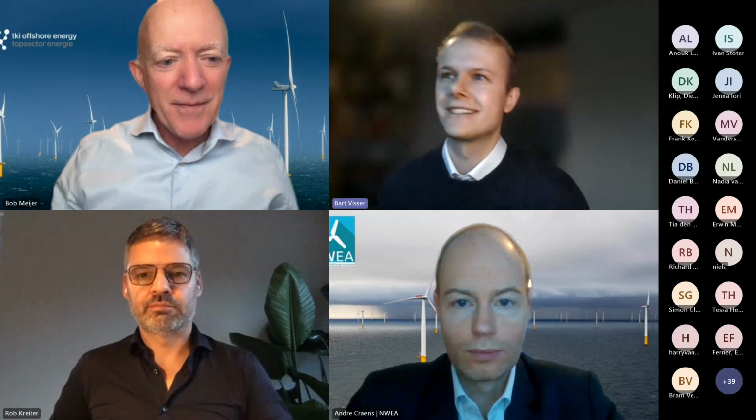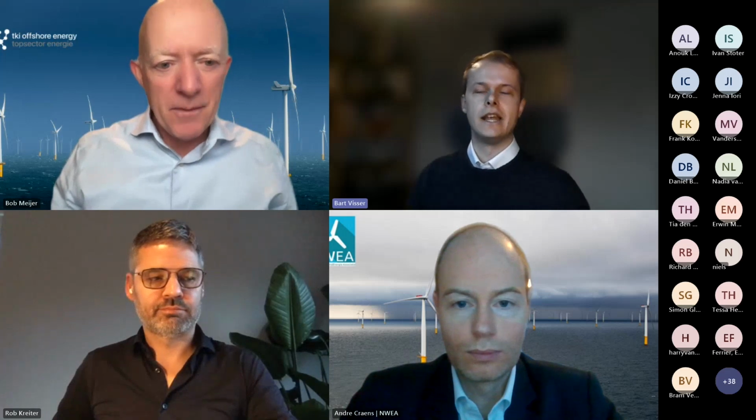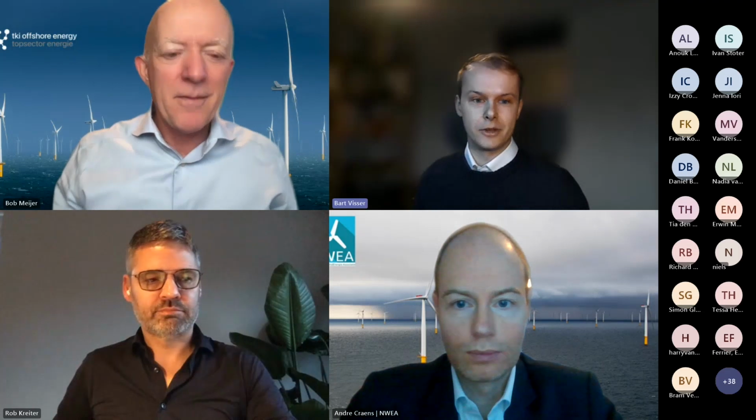Well, let me correct you there a little, because we conclude that both the option of power to hydrogen on land and the hybrid option are very comparable. And in the system analysis that we do, the direct consumption of hydrogen by industry is automatically included. However, the problem that arises from direct coupling of power to hydrogen offshore is that no matter how much wind capacity you have offshore, there are always hours that the wind doesn't blow as hard, so that not all baseload capacity is covered by offshore power production. And if you then exclude part of your wind parks to be directly coupled to hydrogen, even though there is a direct demand for that hydrogen, then you still have additional hydrogen to power conversion with its losses. So it's not directly related to the direct consumption, but more to the electricity consumption.